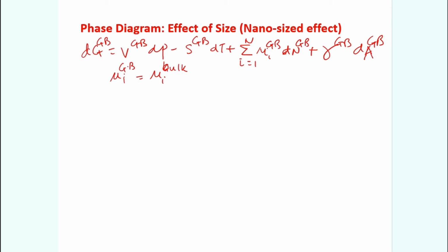But this condition gives that the interfacial energy across the interface, grain and grain boundary, must be the same. Otherwise, thermodynamic stability will not be valid. This is very fundamental. You can derive it. In fact, you can find this in many of my lectures on phase diagrams, thermodynamics of materials, or phase transformation of materials. This equation is derived. These conditions, the equality of chemical potentials of any component in both the phases, must be equal at equilibrium. And secondly, you also need to follow this condition.